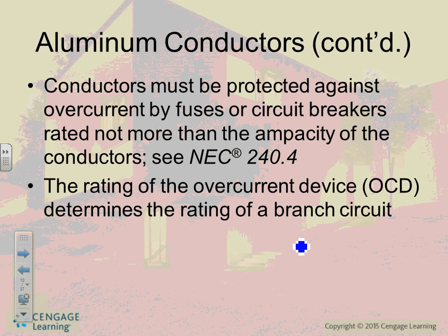It's corrosion, yeah. When you tie copper to aluminum, it's a bad idea. They have a special connector where they don't touch each other. They make a material that takes the copper to the aluminum. The reason is because they expand and contract at a higher rate, and they actually expedite the problem of arcing.